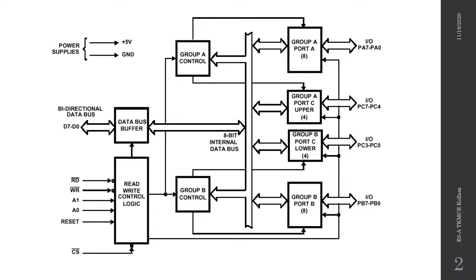Suppose we have one address line, the possible selection combination is that this address line may become either 0 or 1. So the possible combinations are 2. Similarly, if we have two address lines, the possible combinations on these lines are 00, 01, 10 and 11. So 4 possible combinations are there.